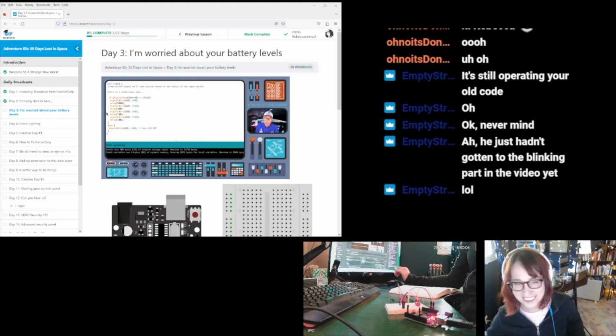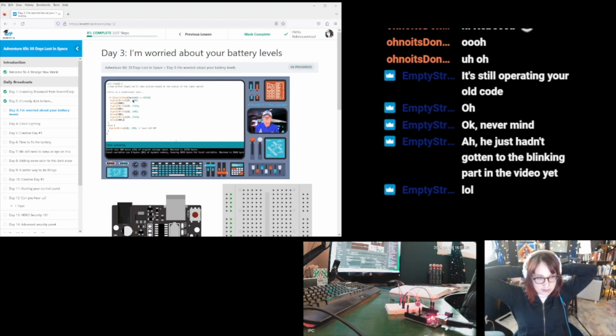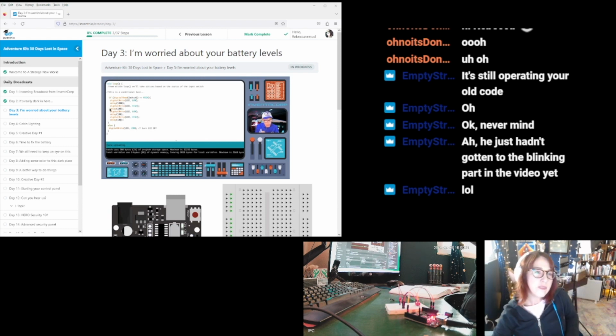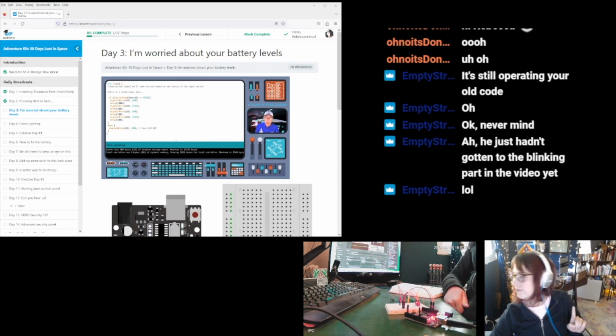And then repeat. So it looks like what we're going to have now when we flip the switch on is a flashing sequence where first we'll have the LED off for a second, then on for a tenth of a second, off for a tenth of a second, on again for a tenth of a second, and then repeat. So it'll be a double fast flash followed by a long pause. So let's see if that works. It does. Go ahead and re-upload our code. It works.